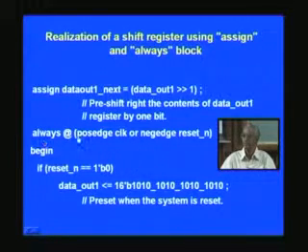Once again, we have an always block at positive edge of clock, we take the action, or at negative edge of reset. And once again, we check the reset condition here. If it is 0, then only what we will do is we will preset rather. It's not resetting. We will preset with the desired value that you want. And notice that 16 is, once again, it tells what is the total width of this data, and this is 16 bits as we have said, so 16 is there, and you also need this quote here, and B stands